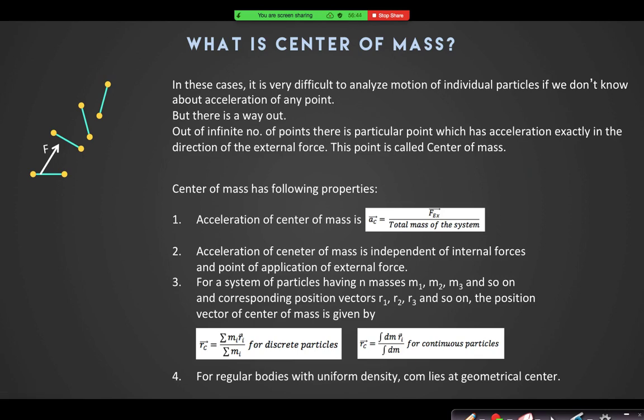Well, now we'll try to calculate the center of mass. In the next few questions, we'll take up a few examples, both discrete and continuous, and try to locate the center of mass. For the center of mass of a triangle, it is the centroid. For a triangular plate, you can say it's the centroid. But for a triangular wire structure, if I just take the perimeter, then it will not be the centroid, even if it is of uniform mass density. If it is made of wire, then the center of mass will not be the centroid. Then you have to calculate it.